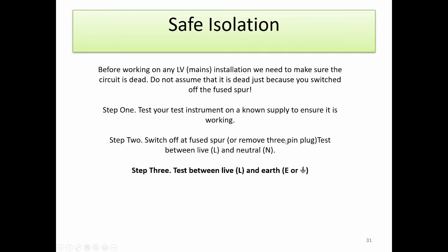Assuming you've got no voltage between live and neutral, the next step would be to test between live and earth. And the last one would be to test between neutral and earth.